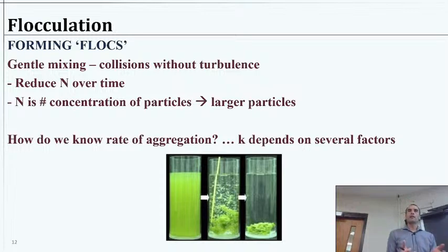What we're effectively going to do is reduce the number of particles. But we don't really care too much at this stage how many particles are there. We just want to increase their size. If we have 10 particles and they all stick together and we assume that their volumes are conserved, like we will assume that, then we've reduced the number of them, but more importantly, we've increased the size. So then they can settle in our sedimentation.